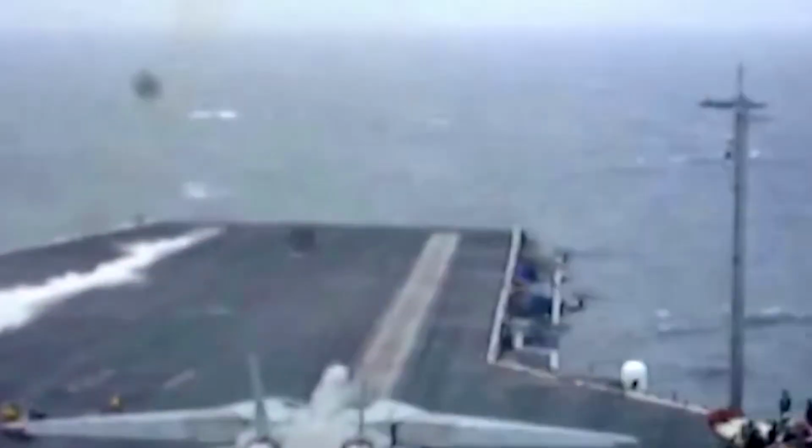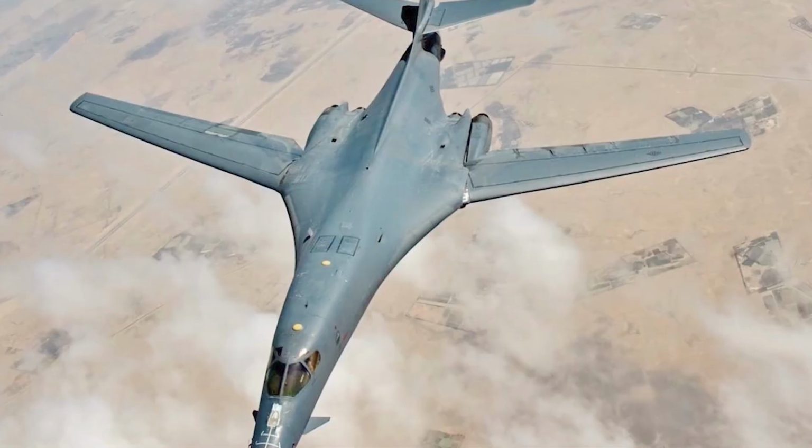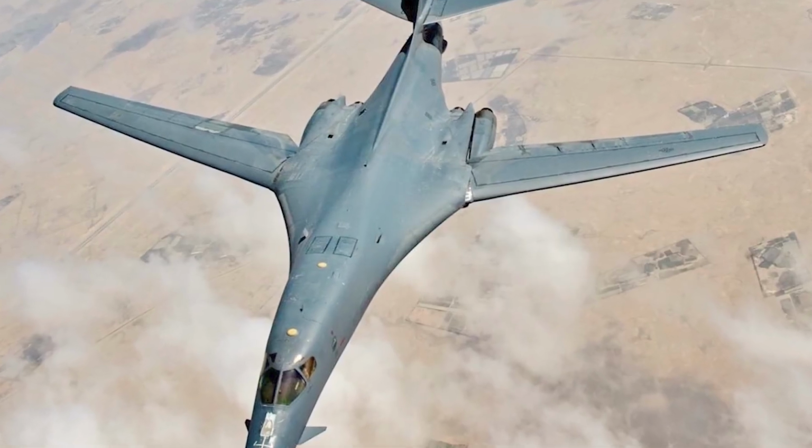This also applies to the B-1, the American bomber, when taking off with a heavy load, as it's a large plane that can carry numerous bombs. So it extends the wings, makes them straight. This gives it a high aspect ratio, and therefore, more lift at low angles of attack. But then, when it enters transonic regimes, it sweeps the wings back, and at supersonic speeds, the wings remain swept.